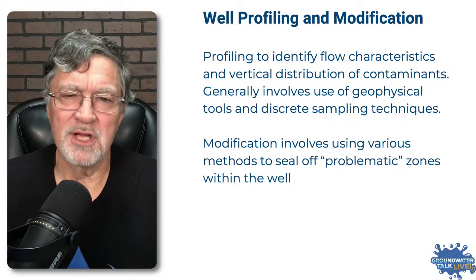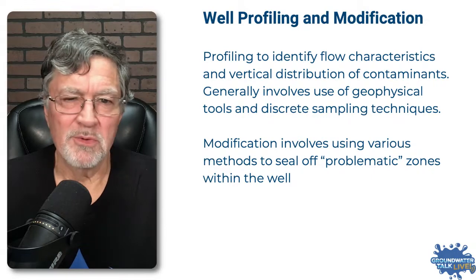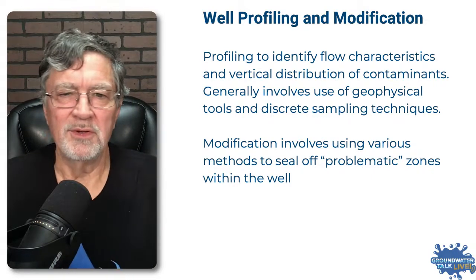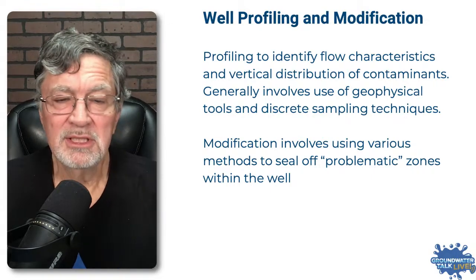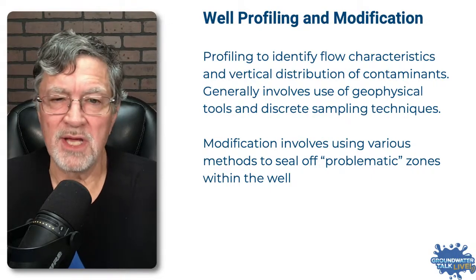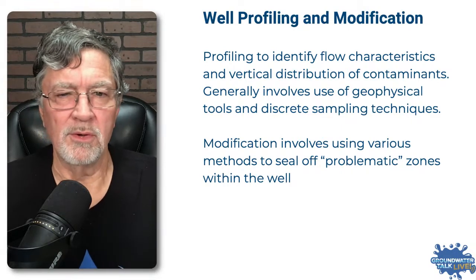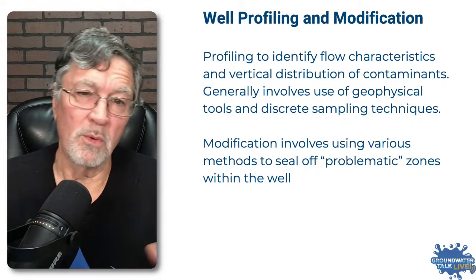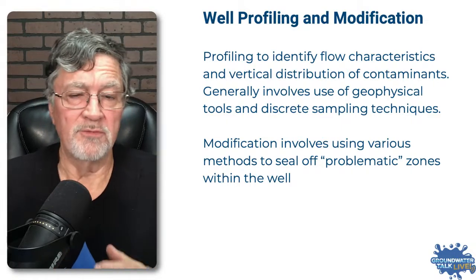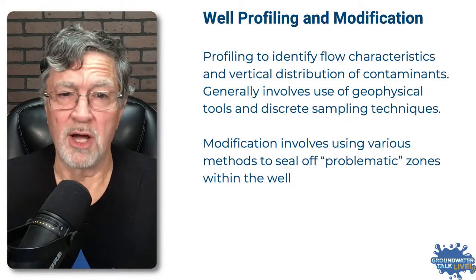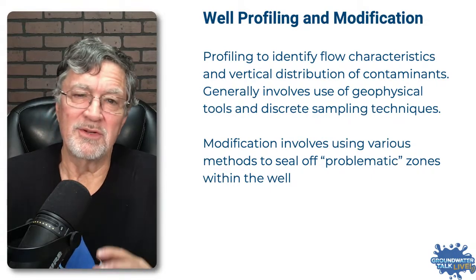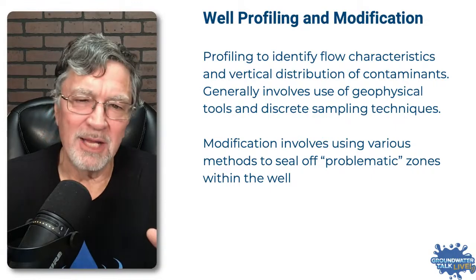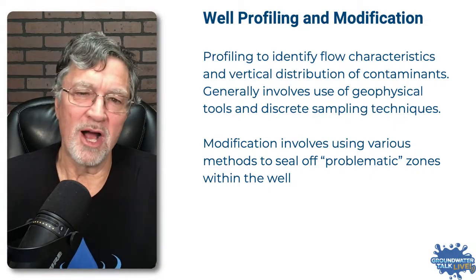There are some different techniques. Fractured rock wells can be a little different. Sometimes you have to pull the shallow casing out or drill it out and get in there and extend the seal down to address certain fracture zones, identify where the contaminants are coming in through these fracture zones, and seal those off. So there's a variety of tools we need. I like to have video too to help guide me, especially on fractured rock wells.